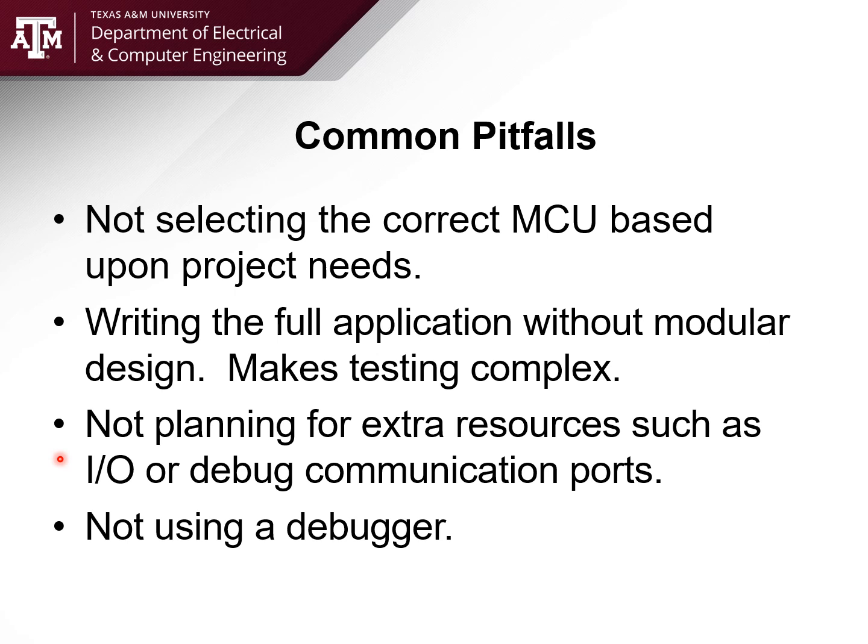There's a couple other system engineering models, but the V model is the one I follow. You enter the project based upon your requirements, and you leave the project based on validating those requirements. So it really comes down to your requirements document. Not using a debugger. This one bites a lot of my senior design students because they think they can use a Raspberry Pi with no debug support, and then they're trying to debug a really complicated firmware project. This really can come back and bite you big time.